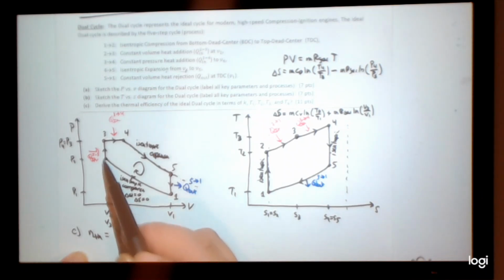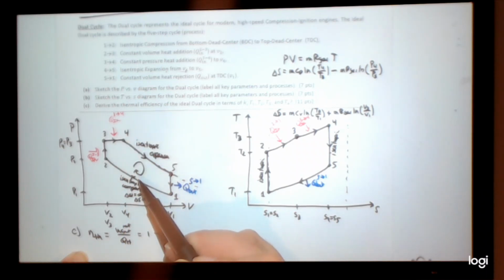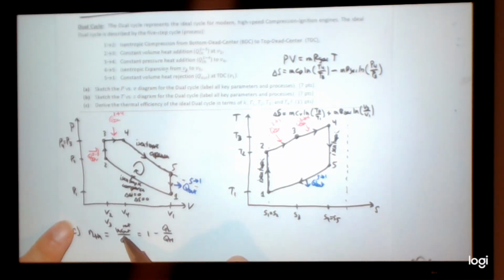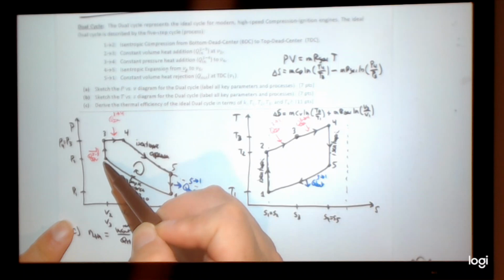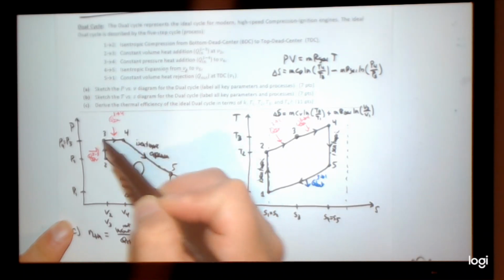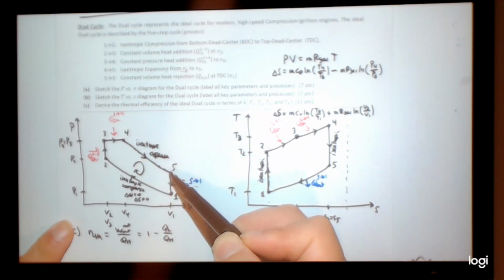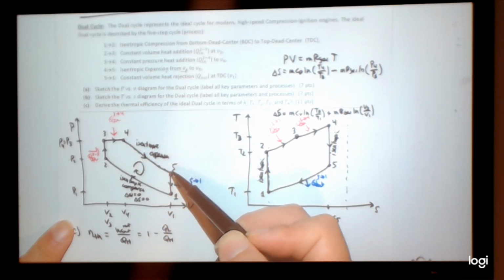So I can calculate this QN, and then add it to this QN, and then get the area under this curve and plug it into here, and I can do it like that, right? Well, to get the work out net, I need to get this integral. This one's easy because there's no change in volume. This one's easier because it's constant pressure. This one, again, is not that straightforward, right? Because I have to use my K's, and then it's a little bit more complicated.